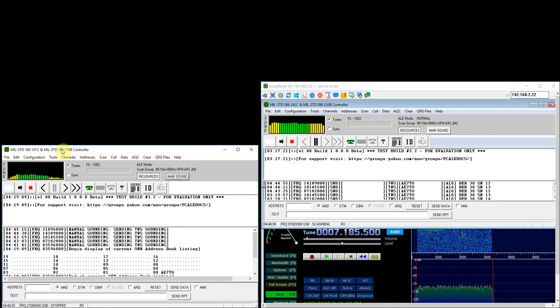And then the other stations, once they've got their equipment set up, would do a manual sounding on each of the frequencies that seem likely to work. And when all the stations have seen the soundings from all the other stations, the net control station would probably be the one to decide what band you're all going to converge on. And at that point, they would want to send a message.